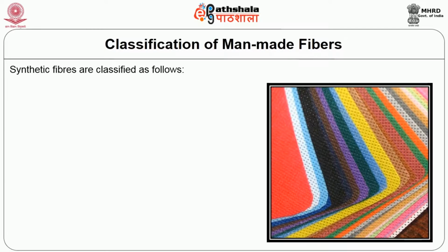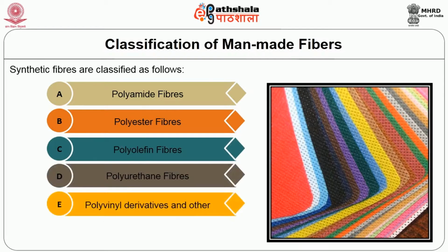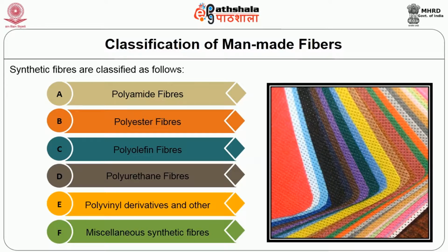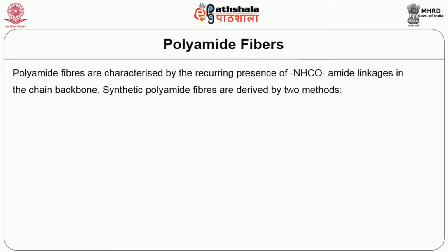Synthetic fibers are classified as polyamide fibers, polyethylene fibers, polyolefin fibers, polyurethane fibers, polyvinyl derivatives, and other miscellaneous synthetic fibers. Now let us go into the deliberation of the polyamide fibers. The polyamide fibers are characterized by the recurring presence of NHCO amide linkages in the chain backbone.